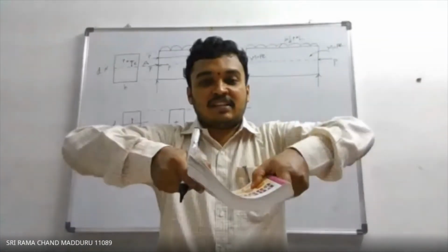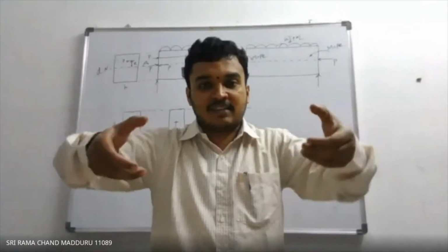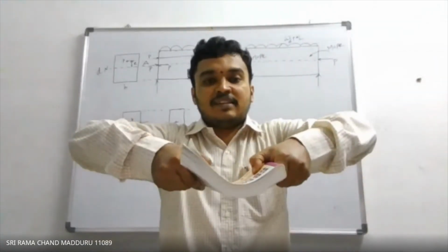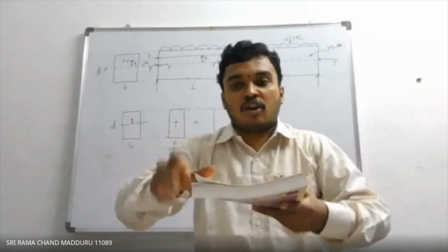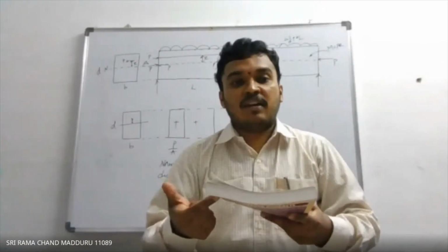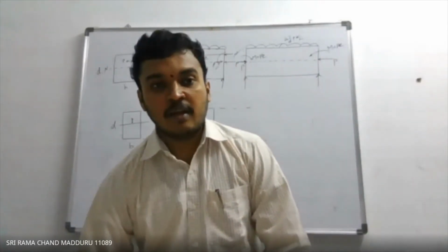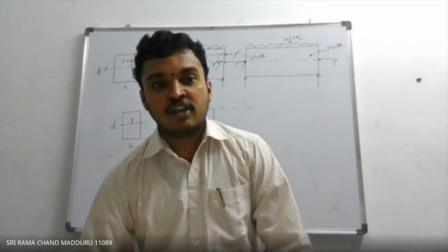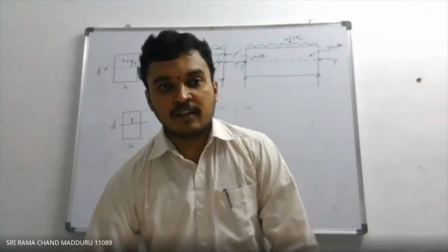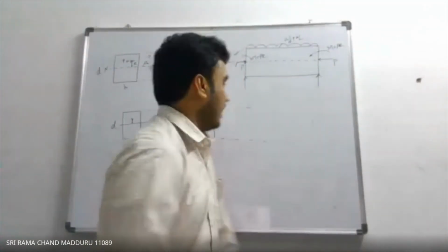There are two moments acting on the beam like this, so the top fiber will be under compression and the bottom fiber will be under tension.